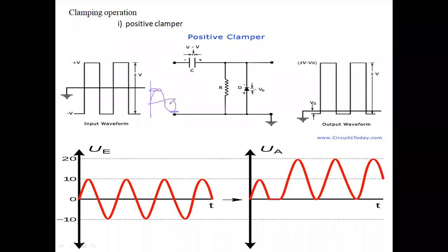If the time constant is low, the capacitor will slowly charge to 10 volts and slowly discharge to 0 volts. It takes more time, and in between this charging, our input may complete around 10 pulses to go to the peak level.